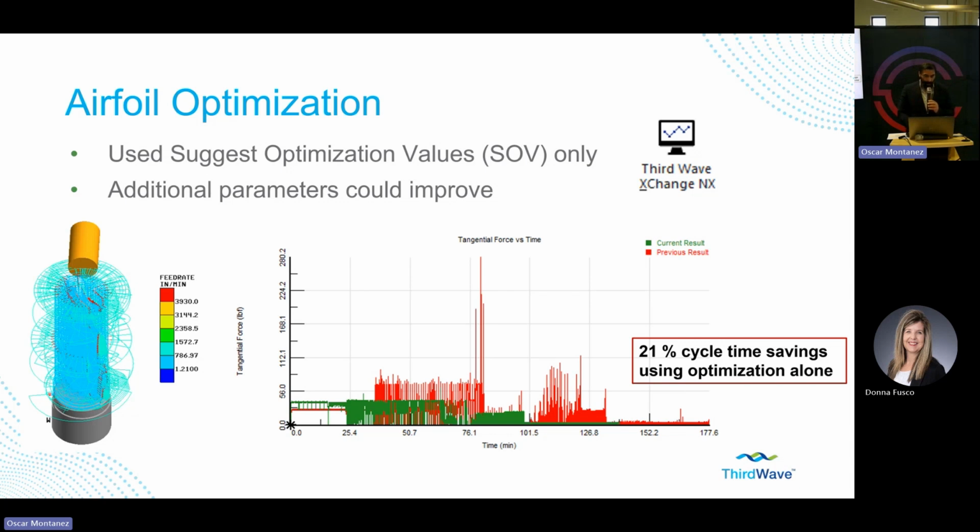So what you're looking at in terms of the optimization is one particular product, Production Module, where our demo is a blade, and the material is titanium. If anybody's cut titanium, it's very tricky. With the other products that aren't being mentioned, Distortio and Advantage specifically, they help with choosing the right feeds and speeds, radial depth, and axial engagement.